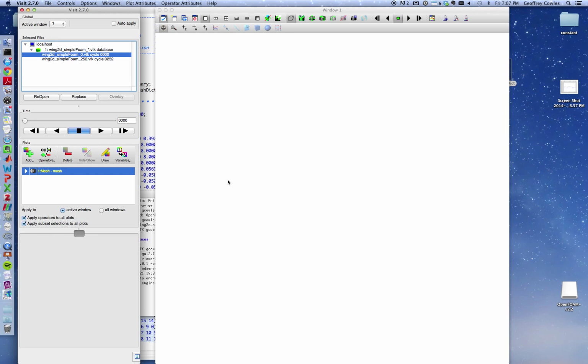So let's see. It's a 2D solution, but again, OpenFOAM isn't ever technically 2D. It's just 3D with nothing happening in the lateral direction. Let me try to slice that. I can't even tell a coordinate. I'm supposed to slice it in X, Z, the vertical. Is it Y? I think it's Y. Okay, so operator slicing. Let's just try it. Nope, I'm going to 0.25. Okay. That's the mesh. It's a little bit hard to look at.